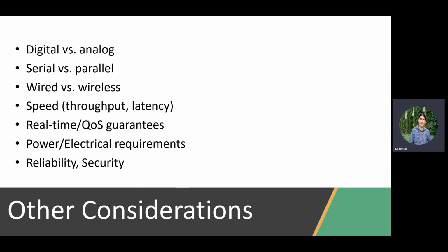Another important factor for embedded systems is real-time or quality of service guarantees. And this is a topic that is becoming more and more common in systems on chip, and even in internal buses as well, not only external buses. I gave you the AXI example from ARM as an example of a very common interconnect in systems on a chip. Originally, AXI didn't have any quality of service. First of all, do you know what quality of service is? What are we referring to?